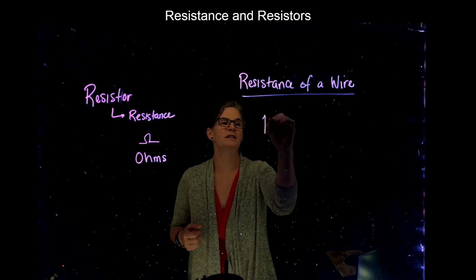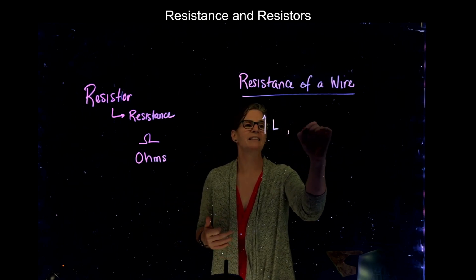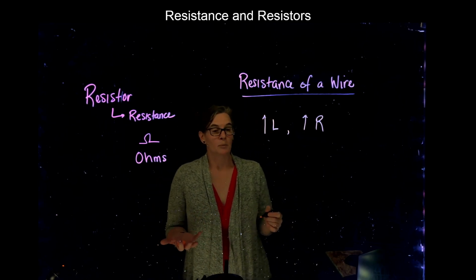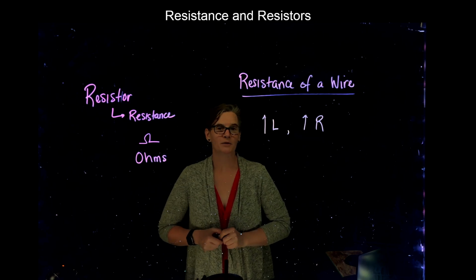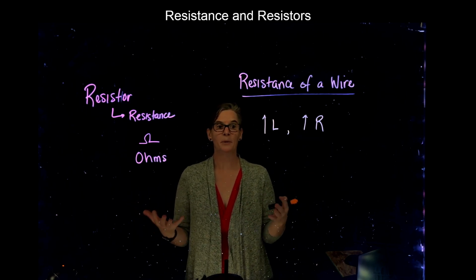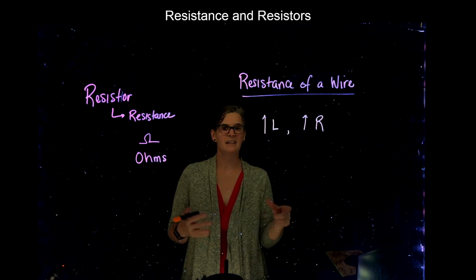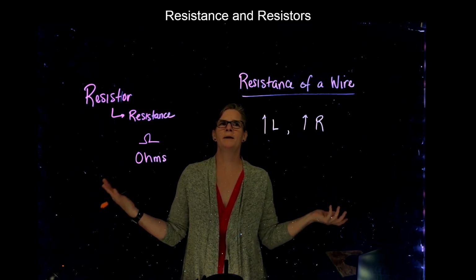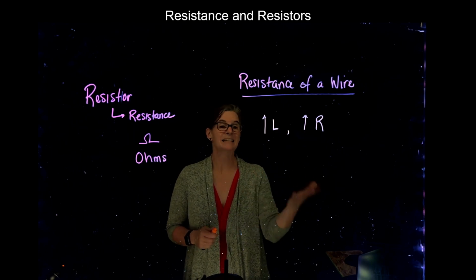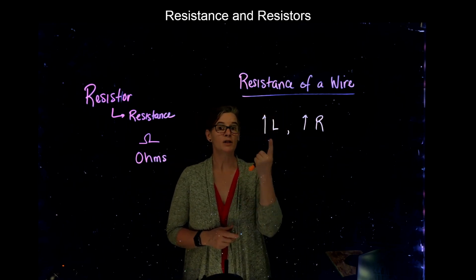If we increase the length of a wire, we increase the resistance. Perhaps you know from your own experience that if you're going to use an extension cord, the shorter the extension cord, the better off you are. If you only have to go a couple of feet, you don't want a 50-foot extension cord. It's because we increase the resistance and we have less current that we can utilize. So there's one example.